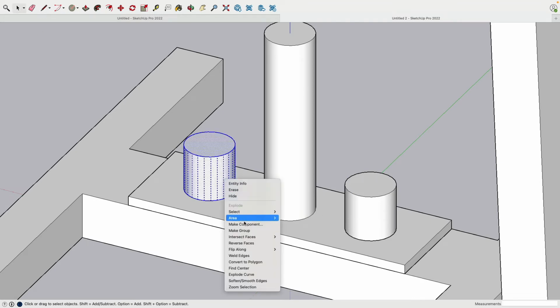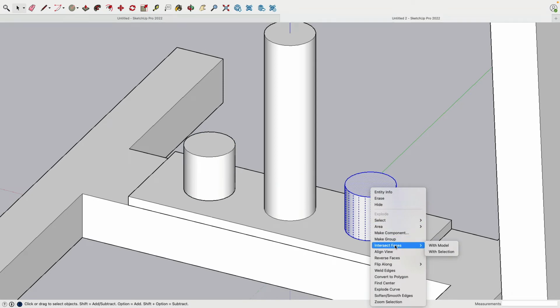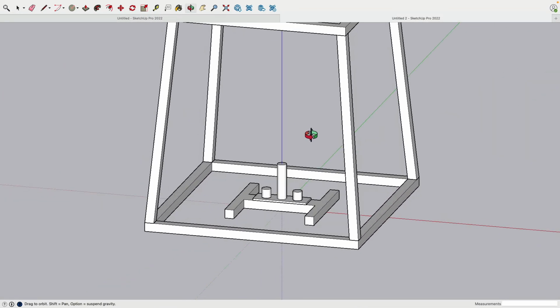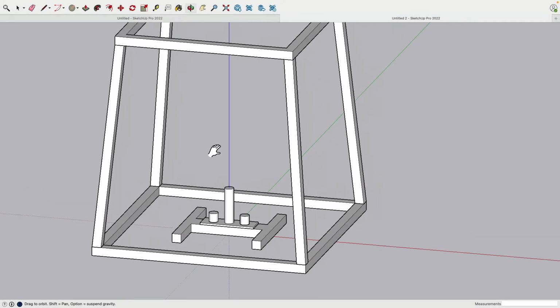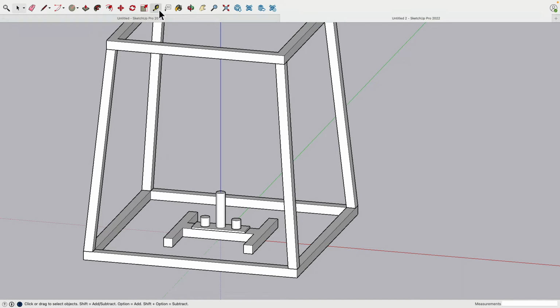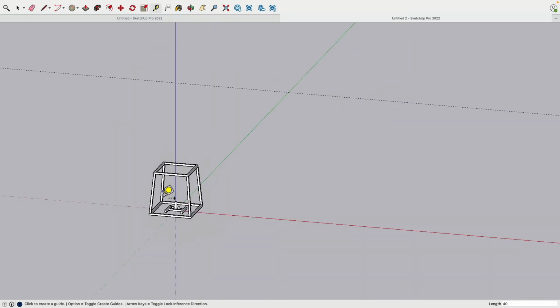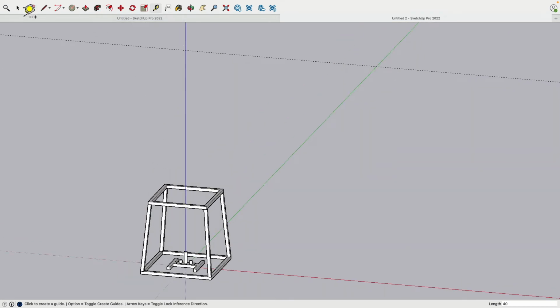To make sure they are not being glued to anything, we create individual groups. Now you see, this is actually quite easy. So let's continue, since we're working on the center point, then the post. But before I do this, I on purpose select an outside edge and move this one up along the z-axis by 40 inches. Cool, now there you see it.